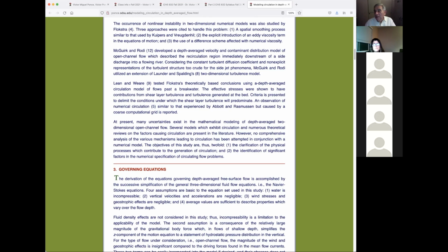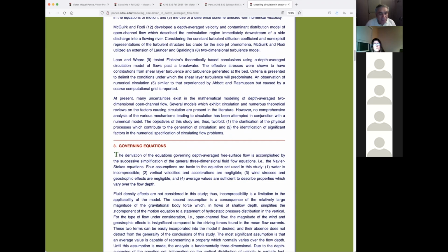And that's the thing about it. And the physical basis is represented by something that I'm going to repeat here today, and it is that the Muskingum-Cunge is grid independent, while the Muskingum is not. So the Muskingum will give you an answer which depends on the discretization. I mean, it'll give you whatever answer you want. If you want this answer, it'll give it to you. That's not modeling. While the Muskingum-Cunge is going to give you an answer. You may not like the answer, but it is an answer. It's the answer of the problem. So it's a better situation.